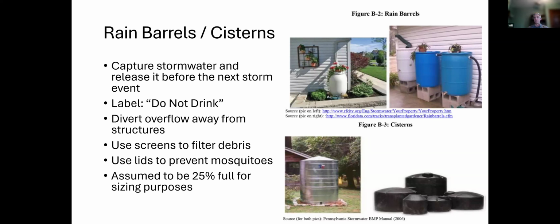You need to use screens or other methods to filter out any leaves or debris from your roof from getting in here and potentially filling up the barrels or clogging them up. They need to be closed so they don't attract mosquitoes.